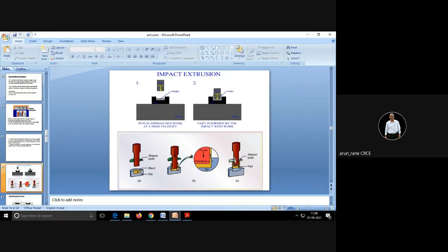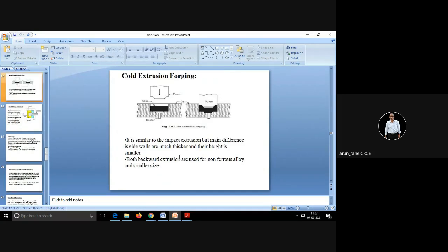Okay. Many times there is a practice that in case the component remains in the cavity, if you are not using stripper, then the people remove the component manually. They remove it manually, of course with the help of gloves. Okay, the component is in hot condition, and if you just try to remove the component with your naked hands, then your hands will get burned. So you should be careful. The operator has to be careful.